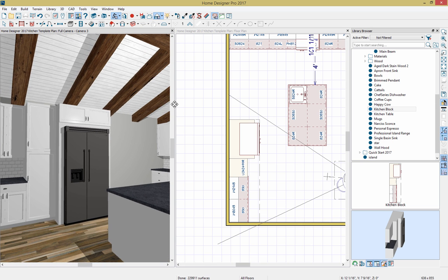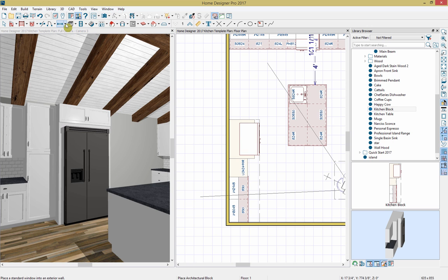And I can see that I have some open space here. So we're going to add in a door. We have different door tools available just as we have window tools, and we can access our door tools on our default toolbar. We can select between a hinge door, a doorway, sliding door, pocket door, bifold door, or even a garage door. I'm going to add a sliding door that'll lead out to our backyard and just click and apply it to my plan. And now that's been updated.